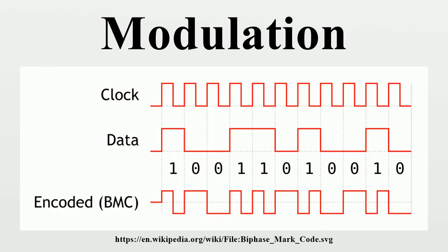The aim of analog modulation is to transfer an analog baseband signal, for example an audio signal or TV signal, over an analog band pass channel at a different frequency, for example over a limited radio frequency band or a cable TV network channel. The aim of digital modulation is to transfer a digital bit stream over an analog band pass channel, for example over the public switched telephone network or over a limited radio frequency band. Analog and digital modulation facilitate frequency division multiplexing, where several low-pass information signals are transferred simultaneously over the same shared physical medium, using separate passband channels.